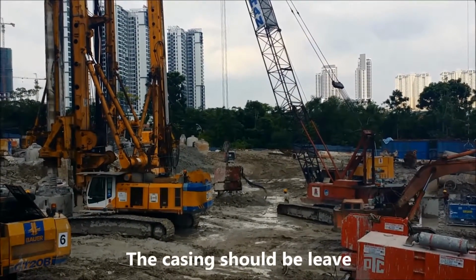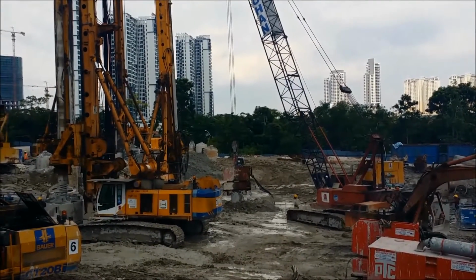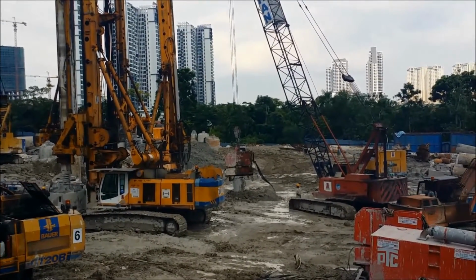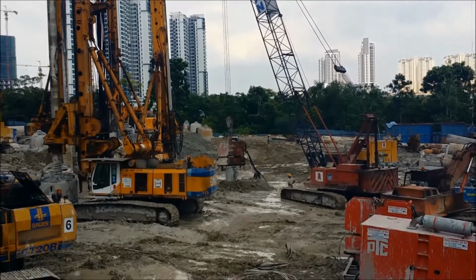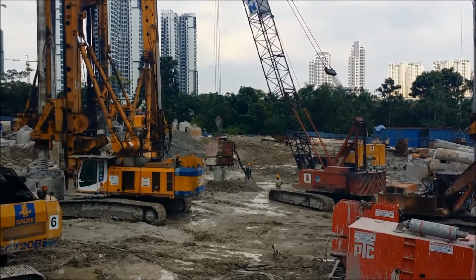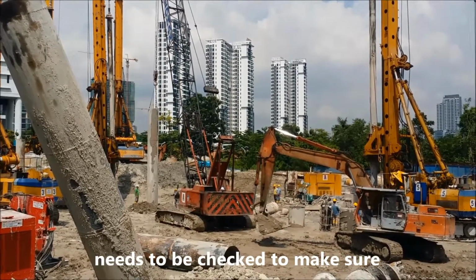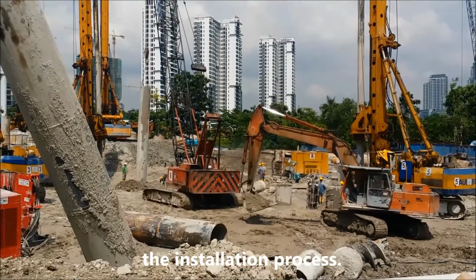The casing should be left 1 meter length protruding from the ground. The verticality of the casing needs to be checked to make sure the casing stands vertical during the installation process.